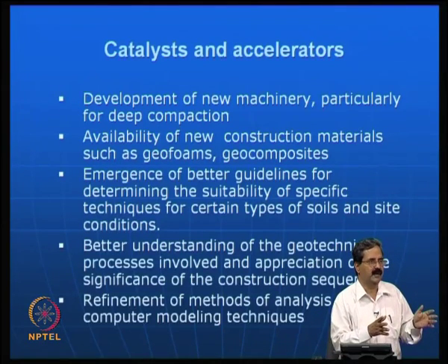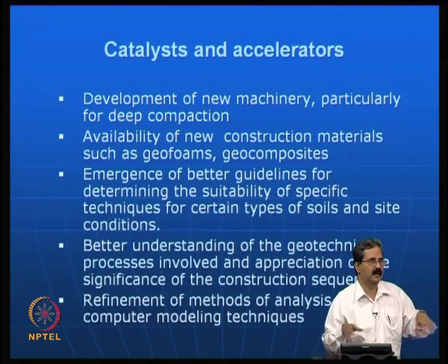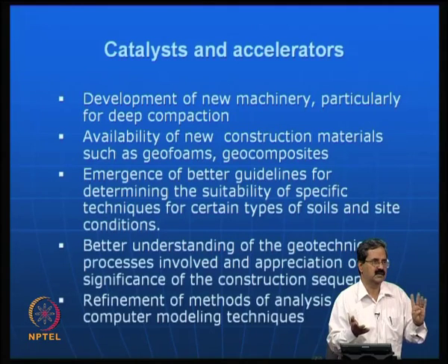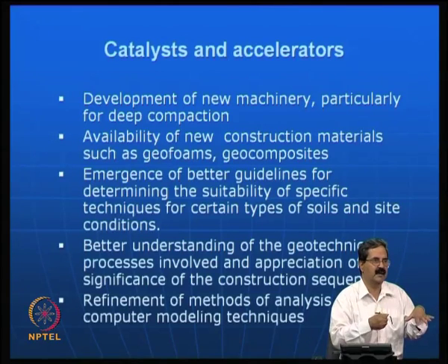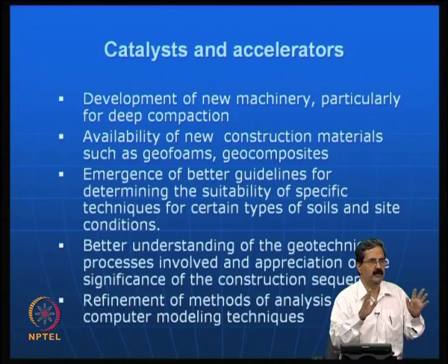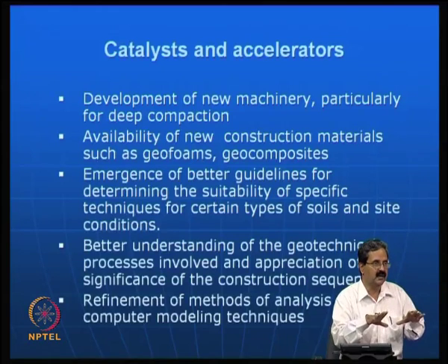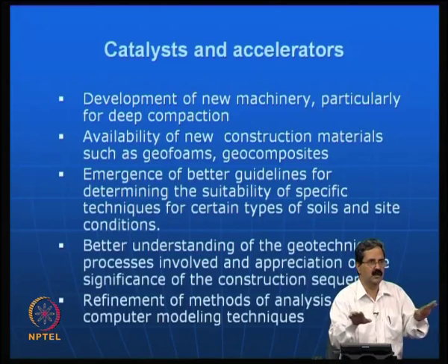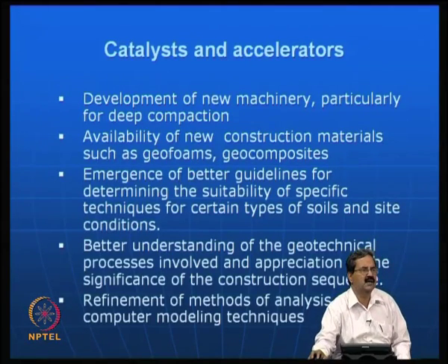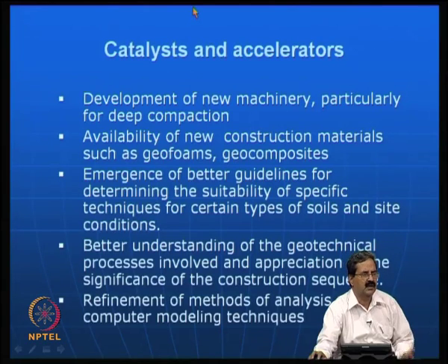The other option, because I do not have a jack and it could be very expensive, is to simply dig it, put the pipe and place the backfill, which can settle in 4 hours. See, if you put soil and start compacting, actually our people will not compact at all, people will be simply slipping there. But here you can use soil plus fly ash, make a mix and pour that, and then the setting time will be about 4 hours. Once it is set, the road is ready, it can be used. I have seen some field examples where such connections are made in no time.